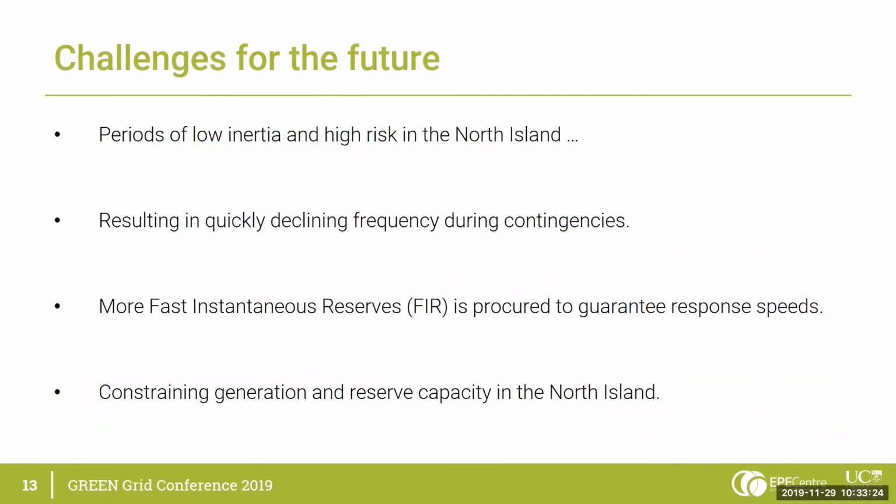So an overview of what I've just said, we should expect periods of low inertia and high risk under high penetrations of wind generation. This will result in quickly declining frequency during contingencies. This requires more fast instantaneous reserve to guarantee that response rate, and therefore generation and reserve capacity will be more constrained in the North Island as a result.